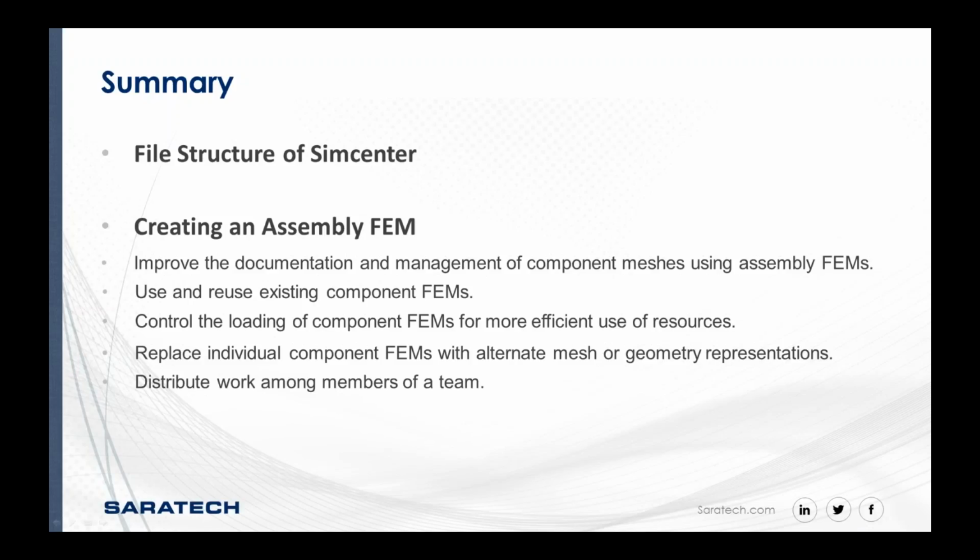So basically what we went over today was the file structure of Simcenter. So you have your idealized part. Understand what your idealized part is: it's doing what-if scenarios, and you're not editing the top-level CAD assembly. And then you have your FEM part, where you're going to define materials, properties, your mesh, things like that. And then you have a sim part where you're going to apply your loads and your constraints, and set up your solution.